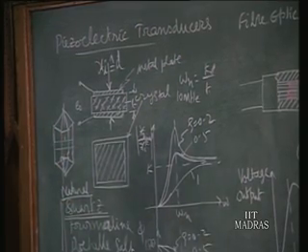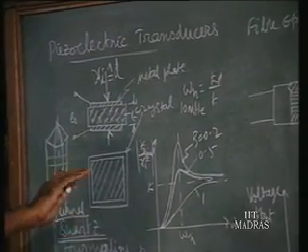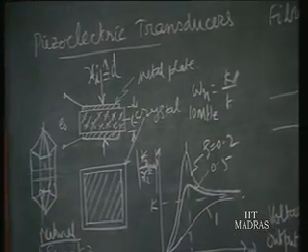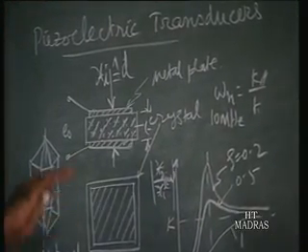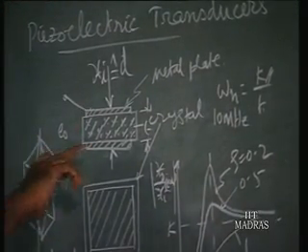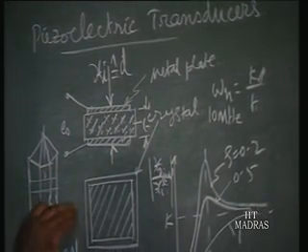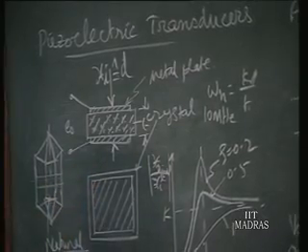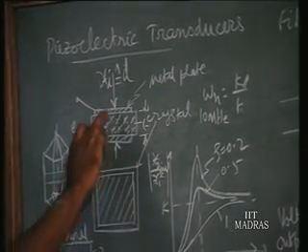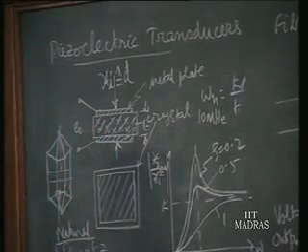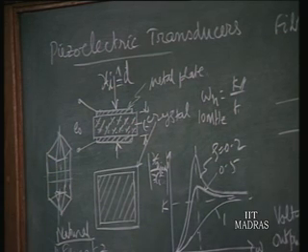So it behaves like a parallel plate capacitor, whose property we have found yesterday. In a simple circuit, with one capacitor in series with a resistance, across the resistance we take the output. That output we find is there only for dynamic signals. For static displacement, this charge will be 0. As per the previous class, this single capacitor responds only to a dynamic signal.